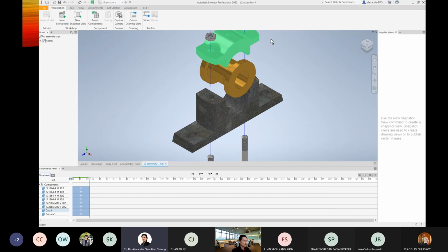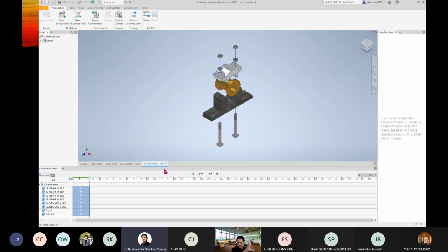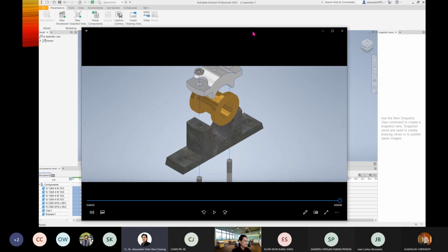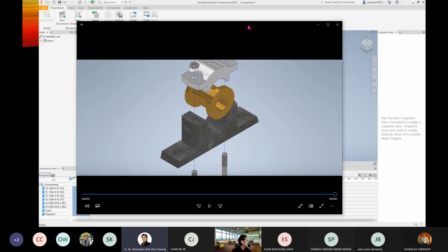If you would like to have the full view, then better you open your exploded view, F6, and then start recording, create the video in this way, so that you have the full of it. They record your current view as it is. But anyway, that is how you produce the video, the animation of your exploded view.